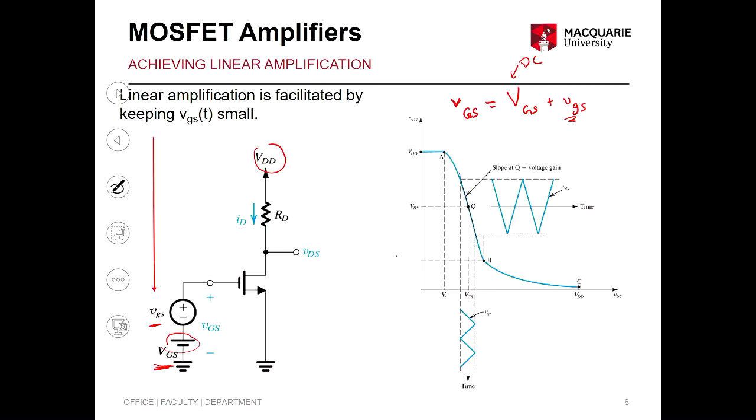Now what it simply says is that depending on your signal, as we talked about, you get an amplified signal. The other thing that is important here: what can you tell about the output signal with respect to the input signal? Obviously it's amplified. The other thing is it's inverted, right? Because when you increase that way, you go down this curve. So that's the increment in here, and that's a decrease in here. It just inverts, 180 degrees out of phase. That's all.